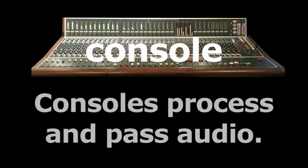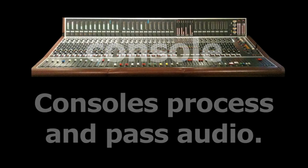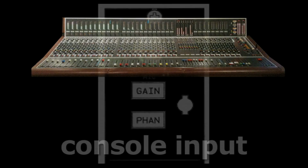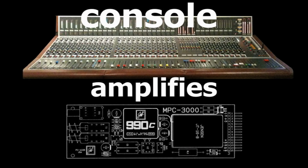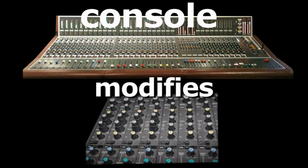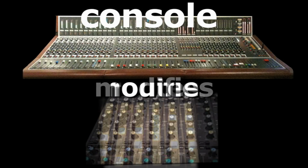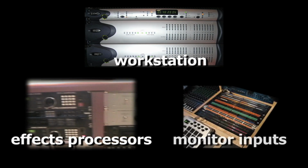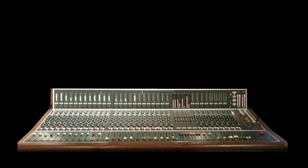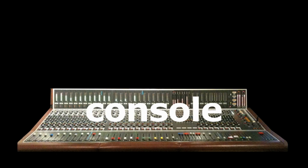However, the big difference is that consoles actually process and pass audio signals. The signals enter a console usually at either mic or line level. The console then amplifies, for example, increases the gain from mic to line level, modifies using signal processing like EQ and compression, and then routes the audio signal to the desired location, like workstation inputs, outboard effects processors, or monitor inputs. Some mix engineers prefer to use consoles because of the additional functionality they bring.